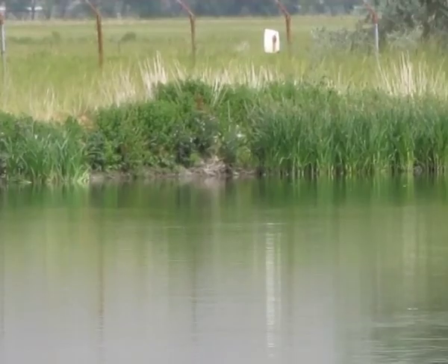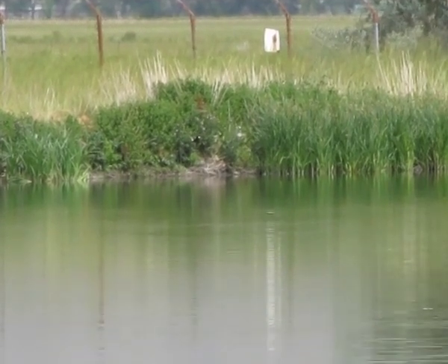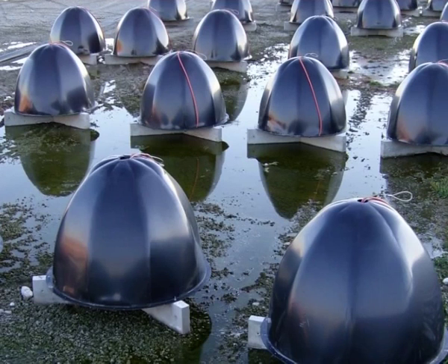Aerated lagoon system is another treatment plant employed in liquid waste treatment, which is generally used where there is not sufficient land available for seasonal retention or land application, and economics do not justify an anaerobic or activated sludge system. Efficient biological treatment can be achieved by use of aerated lagoon system.